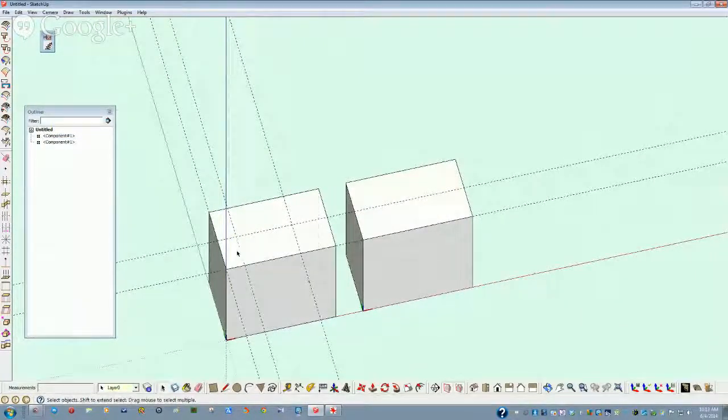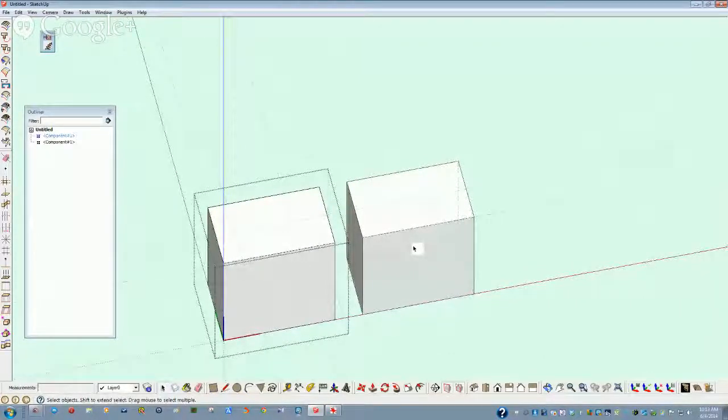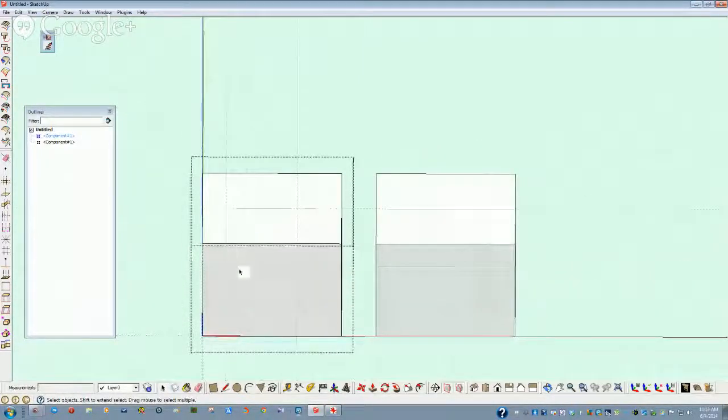And I'm going to put 2 holes. You didn't see them go over here because I was not in my component. That's always a mistake when you do not verify that you are actually in the area you want to work in. I'm going to make this one 3/16. I'm going to use these for 3/8 dowels.